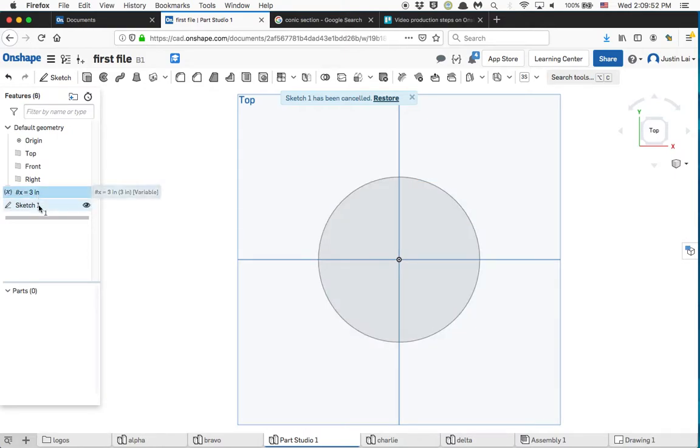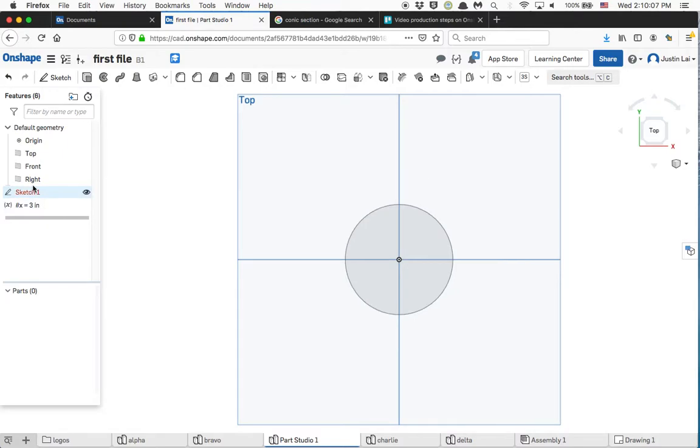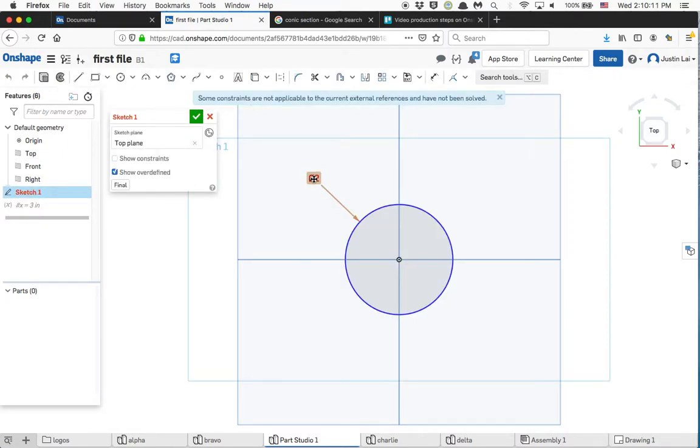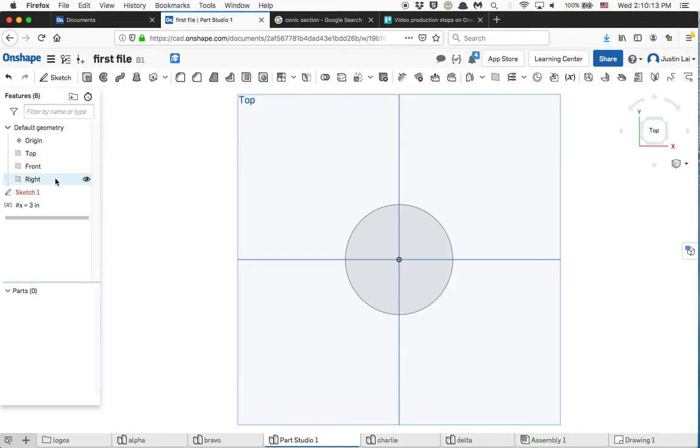And then with these variables, you can define whatever letters and significant names up front. Make sure they're up top, because if you put them out of order like this, Onshape's going to say, hey, sketch 1 is the first thing, and there exists no variable called x, so make sure you are in the right order.